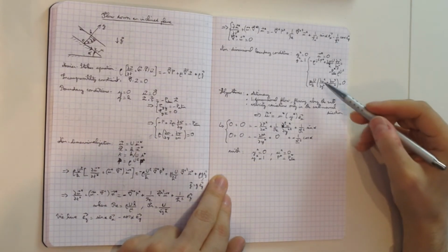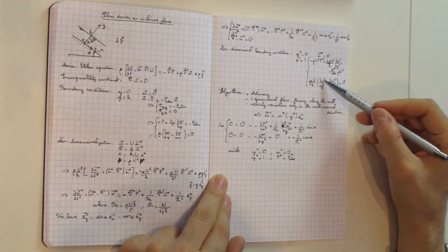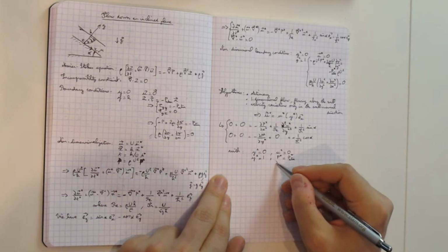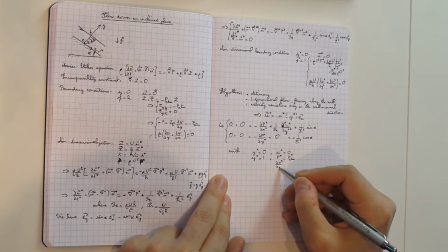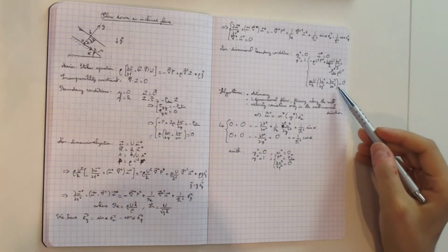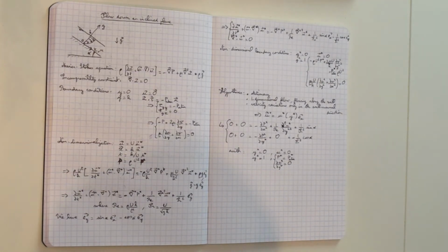And then for this last equation, first of all, mu u over h just simplifies because it's a prefactor and the right hand side is 0. But also u depends on y, so that's fine. I can keep this term, but this is identically 0, so I do not keep this. And what I get ultimately is du star by dy star equals 0 for this boundary condition. That essentially tells us that there is no friction. There's no tangential stress at the boundary. Okay? So these are our equations with the boundary conditions. So now we can just solve for the flow.